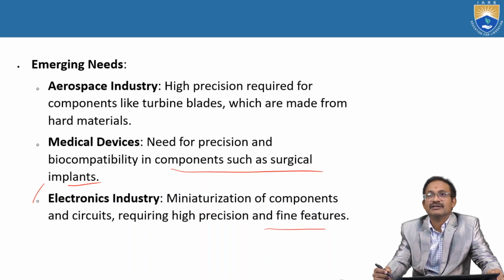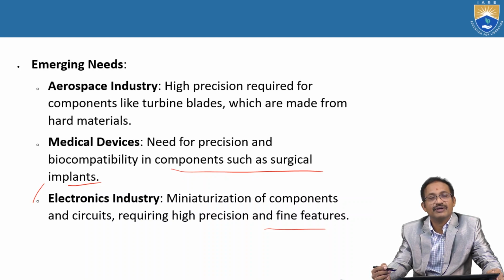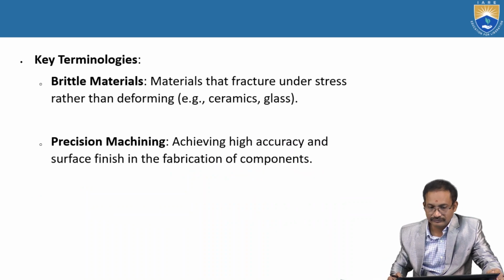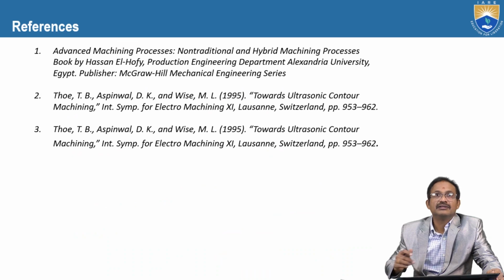But to semi-finish the raw material into semi-finished goods, we go with conventional machining, and to some extent CNC machines. For very precise holes over surfaces developed by CNC machines, we can use unconventional machining processes. Very minute holes cannot be made using conventional methods. So with this, let me conclude.